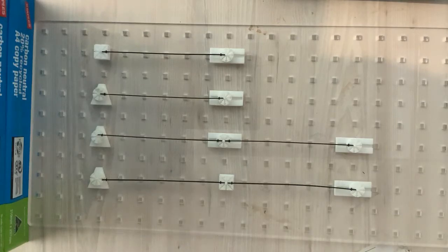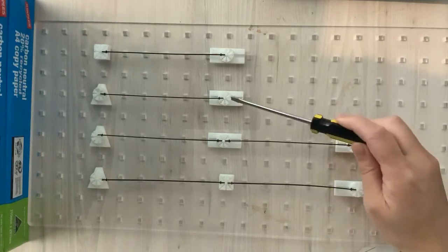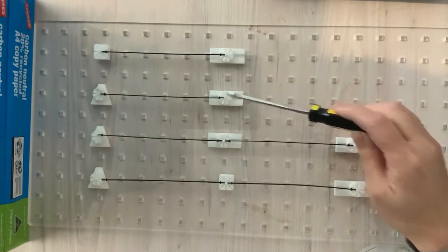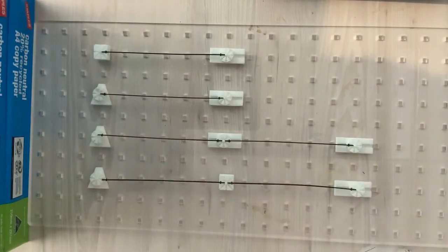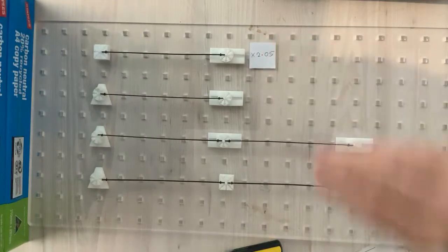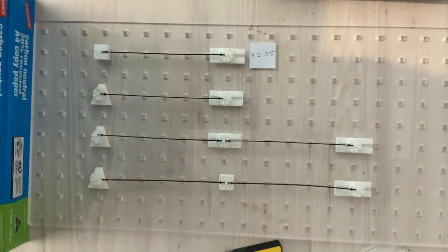So moving from here to here, what's happened is that we have changed the boundary conditions. This one has rollers at these two ends, and then this end is a pin, and then this end is fixed. As a result of changing the boundary conditions, compared with this case here, the Euler load increases by a factor of 2.05, which is exactly the number that you're reading off in your course book.